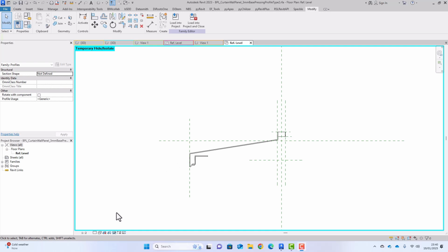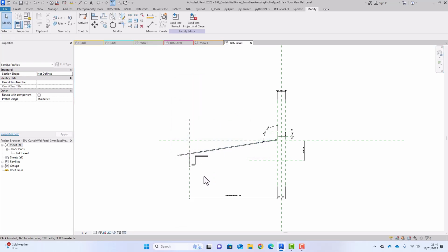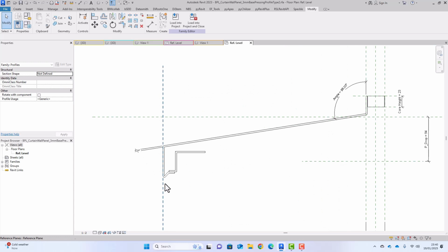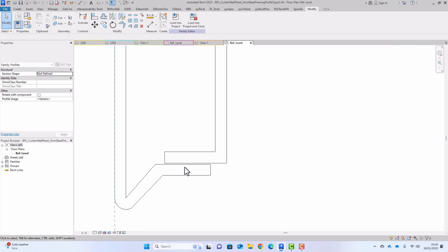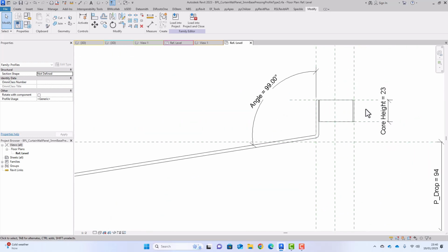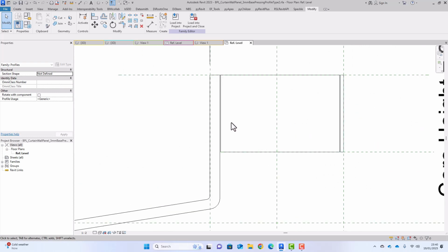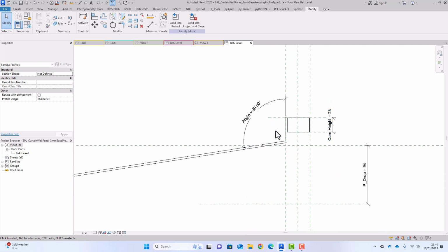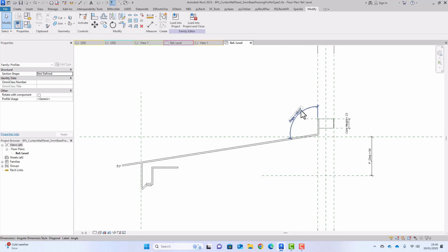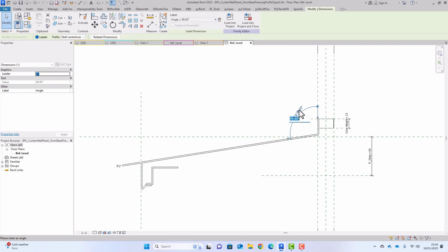So once you've created your dimension, from the dimension you can have your parameters. I'm going to just reset everything, I've already saved it. So these are my dimensions, and from the dimensions I've created the parameters. You can see within each profile I've left a gap of 0.2 mil, and even here as well, just to create an illusion. The gap can be within 0.2. This is the closest it can be, and it's not going to constrain. And from there you create your parameters.